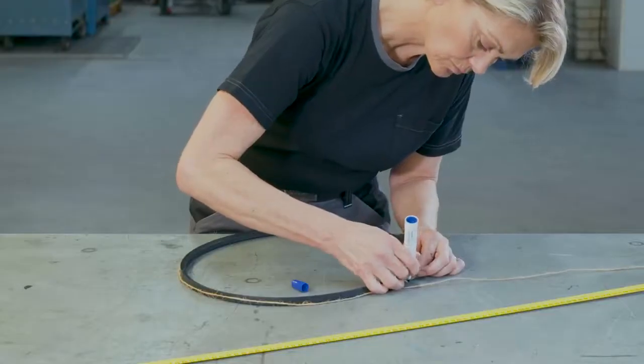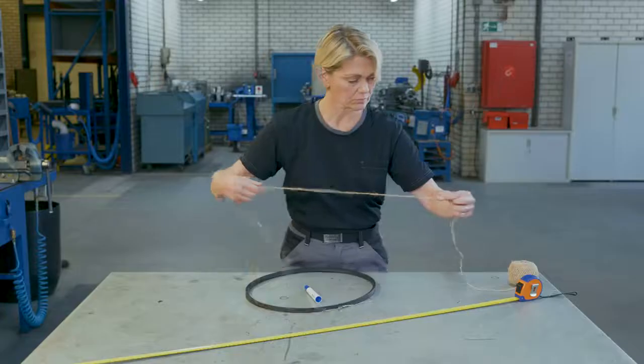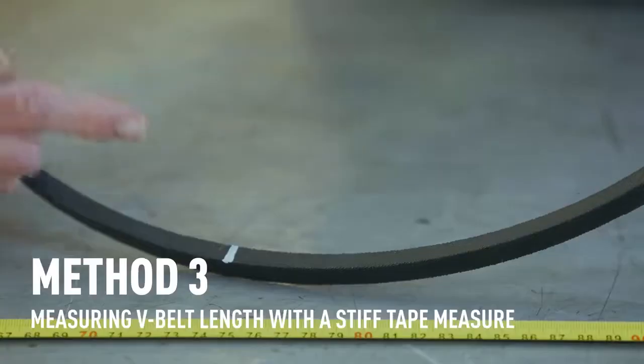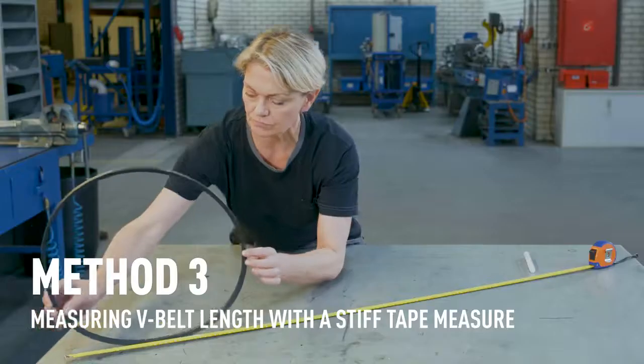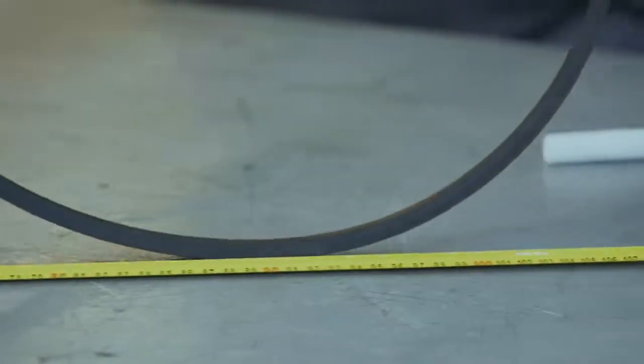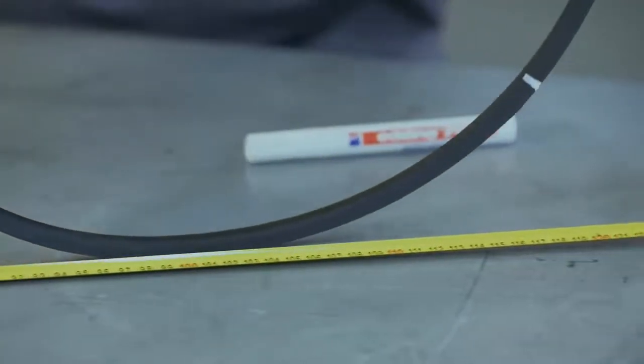Mark the string when it gets back to the starting point again. Then measure the length of the string with a tape measure. Number 3, clearly mark the belt and then roll the outside of the belt, starting at the marked point, along a stiff tape measure until you reach your mark again. This will give you a rough idea of your measurement.